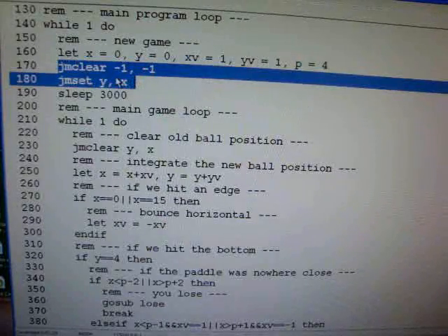Basically, we can run the exact same version of this operating system on the 51JM128, the 52221, the 52233. There are only 3 statements, two of which are these, that we've added to the badge board to make the badge board experience a little more badge board unique. That is, we've added the ability to manipulate the LED matrix. You can set and clear individual or groups of pixels on the LED matrix using the JM clear and JM set commands, and you can also scroll text asynchronously across the LED matrix using the JM scroll command.